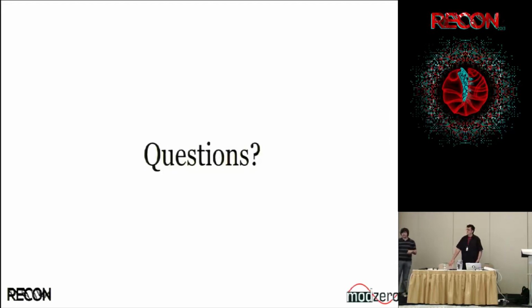Everything is a terminated design. Okay, it means that the buffers need to be able to handle some negative signals and generate them. Is that possible? No, but you can completely disable the buffers. You can bridge them. You can pretend they're not there. This is completely doable. So if you want to implement your own termination scheme, do custom I/O, LVDS using crazy $10 chips from TI doing SerDes and then trying to read it back as fast as you can, you could try this. There's no reason it shouldn't work. But this is not something that the board can do as is. You would have to build some custom hardware to go with the board.